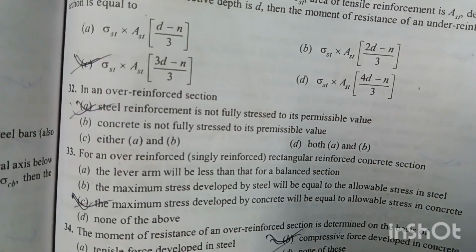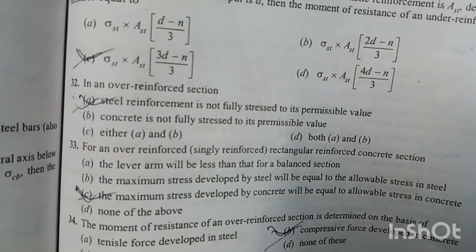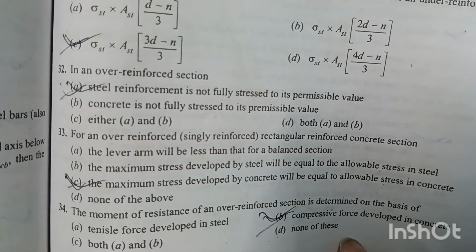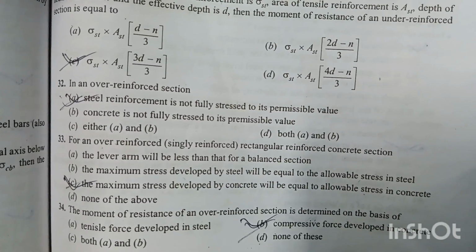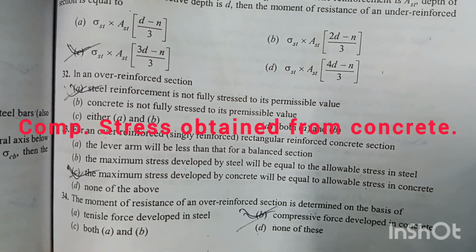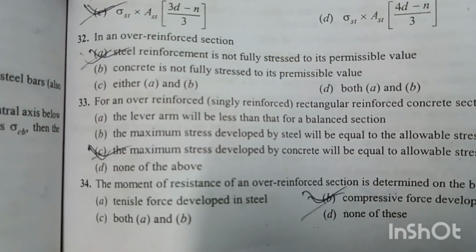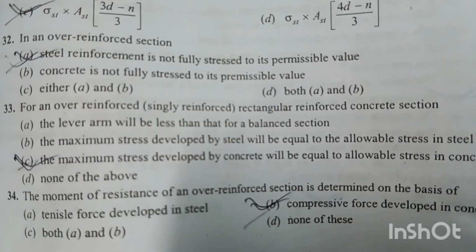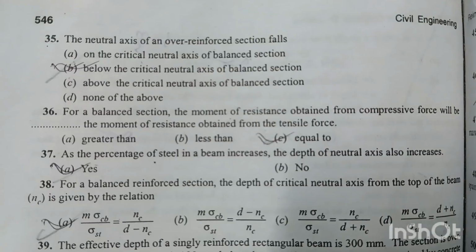Question number 33. For an over reinforced singly reinforced rectangular reinforced concrete section, the maximum stress developed by concrete will be equal to allowable stress in concrete. Option C is right answer. Question number 34. The moment of resistance of an over reinforced section is determined on the basis of compressive force developed in the concrete. Option B is right answer. And the moment of resistance of an under reinforced section is determined on the basis of tensile force developed from the steel reinforcement bars.